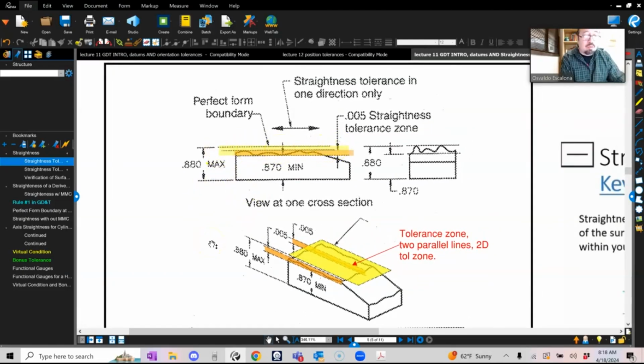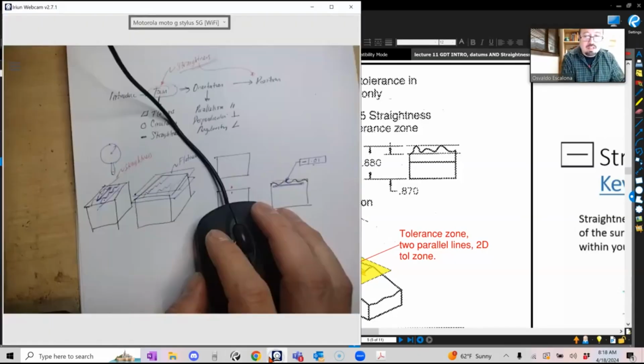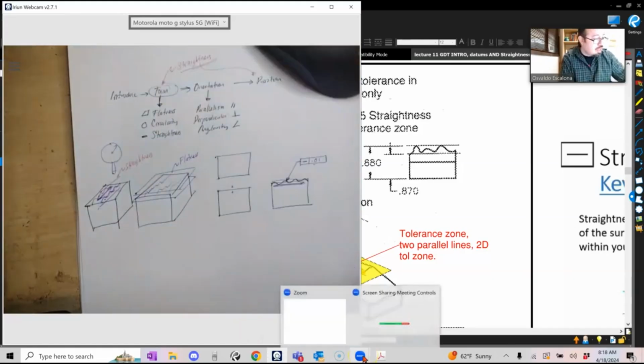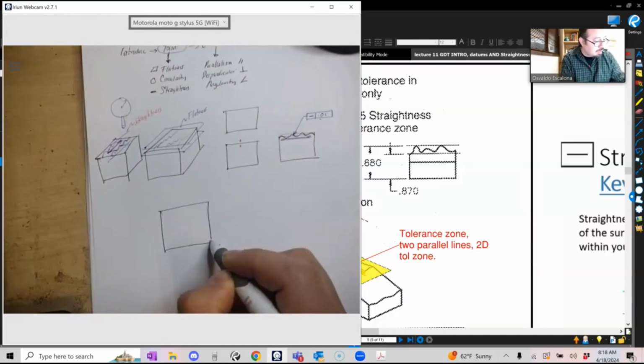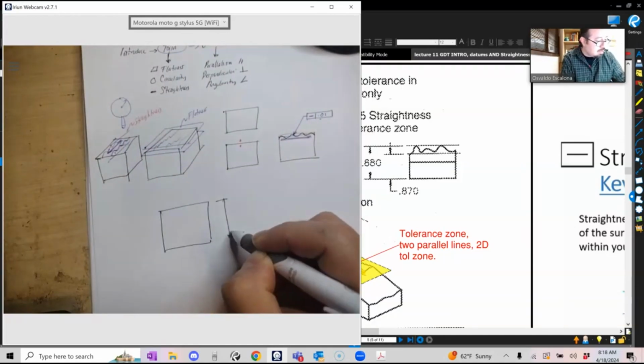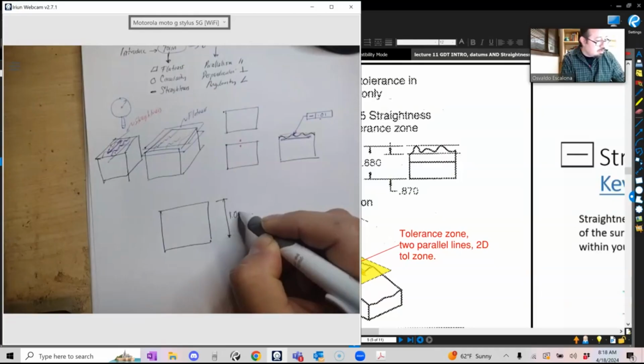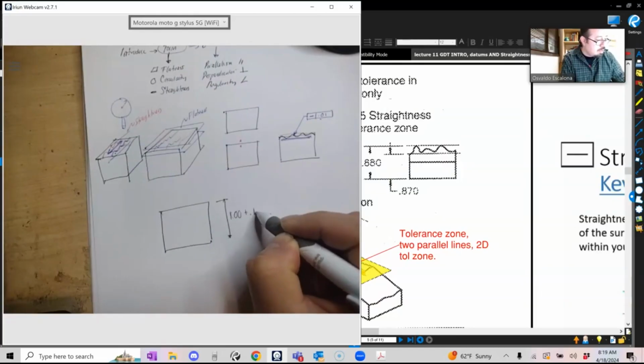And if I want to use both of them, that means that I just have a refinement on one within the other, okay? And again, at that point you might have one within another. It's just refinement. All the form tolerances are refinement on each other. So again, I could have a part which has a distance, let's call it this guy, 1.00 plus minus 0.10, right?